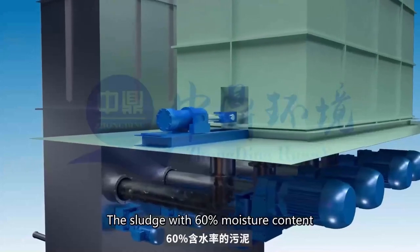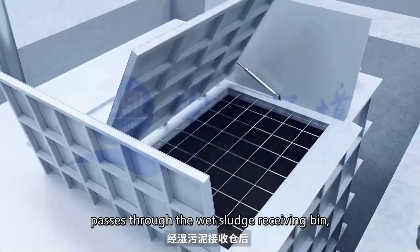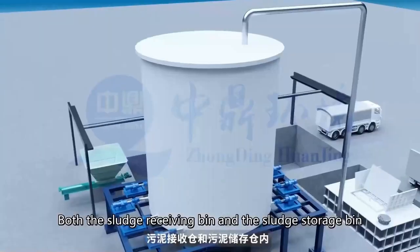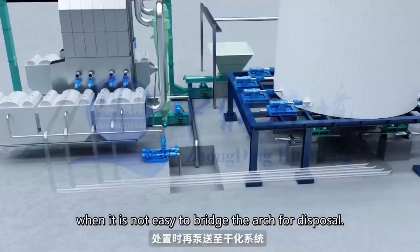to transport sludge to the drying system. Sludge with 60% moisture content requires a buffer silo with skids to ensure uniform feeding. Sludge with 80% moisture content is first pumped to the wet sludge receiving silo and then to wet sludge storage for temporary storage. Skids can be arranged in both the sludge receiving silo and the sludge storage silo as required, ensuring smooth flow of sludge and preventing bridging. It is then pumped to the drying system.